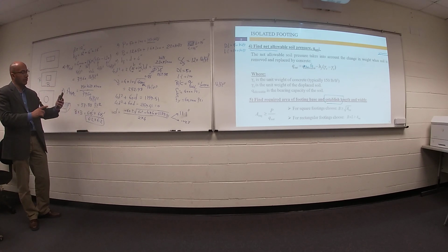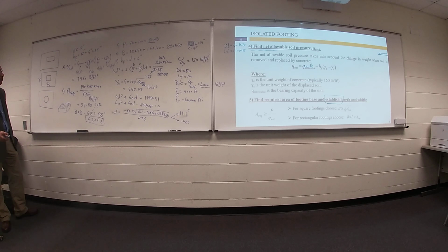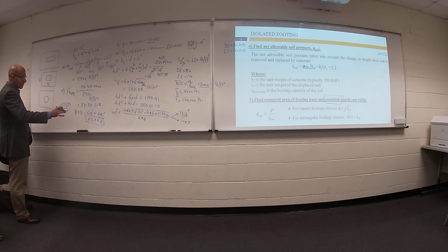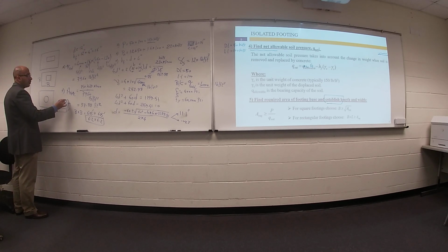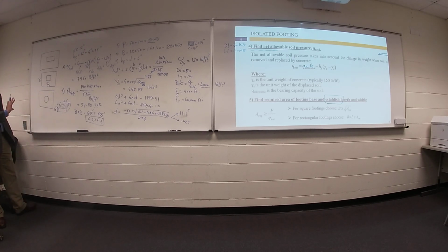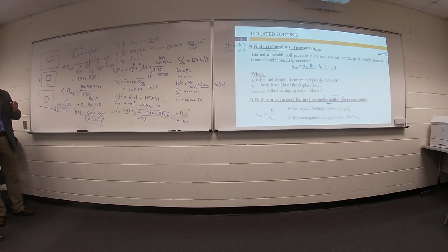36.2 times 6.2 equals 38.4, which is greater than the area required. So now I can tell you your total thickness of this footing equals 16 inch. This dimension will be 6.2 feet times 6.2 feet. All of these calculations are just to determine the dimension of your footing.